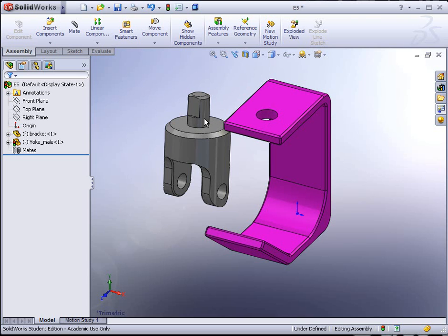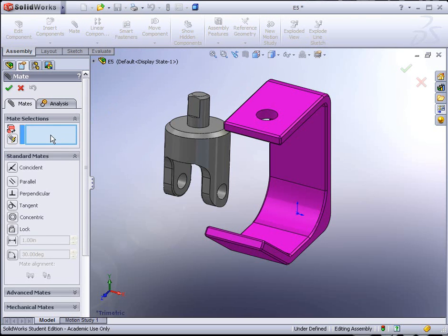What I like to think of is that you select the faces or edges that you would add glue to if this was a plastic model that you bought at the store. So first of all, there's the paperclip icon. This is Mate. This is what you're going to be using quite a bit to attach these parts, to paperclip them together, so to say. So select the mate, and it's asking to select the entities to mate.